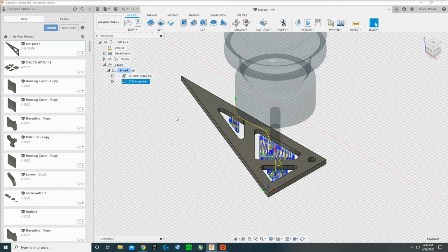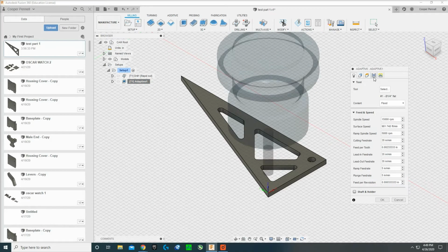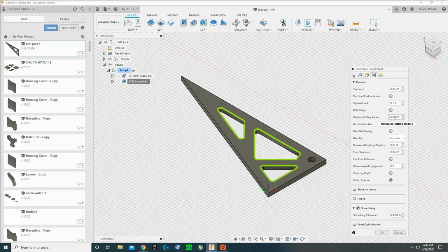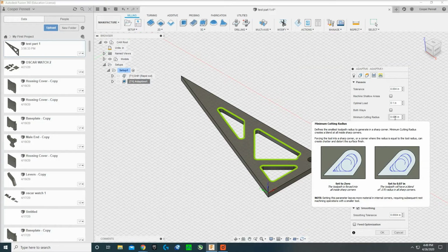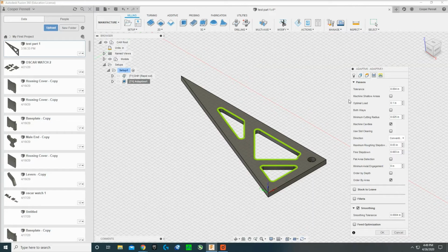So one of the common examples of this is if you have a 0.25 inch bit and you're asking it to make a 0.26 inch hole, that's a very, very small cutting radius, which, like I said before, if you go in here, if your cutting radius is 0.025, it's not going to do it, because you've got a 0.25 bit plus this 0.025, which makes the minimum cutting radius of a hole 0.275, which is larger than the 0.26, right?